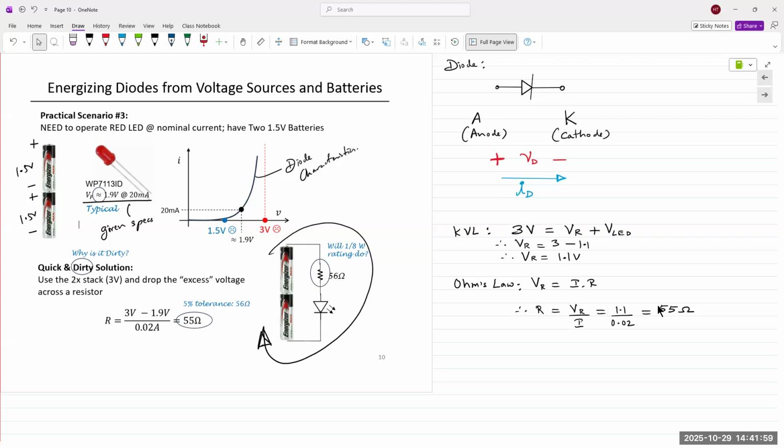And that's a flashlight. If you have a regular filament light bulb, then you don't need a resistor because the filament itself is going to provide the resistance, right? The operating principle of a filament light bulb is that it opposes the flow of current. And when it opposes the flow of current, it releases energy in the form of heat as well as light. So while it provides light, an incandescent light bulb also gets hot. So all types of flashlights, I still have one in my toolbox. You have those small filament light bulbs, and you can put that across a 3 volt battery, and it'll turn on. No resistors required.